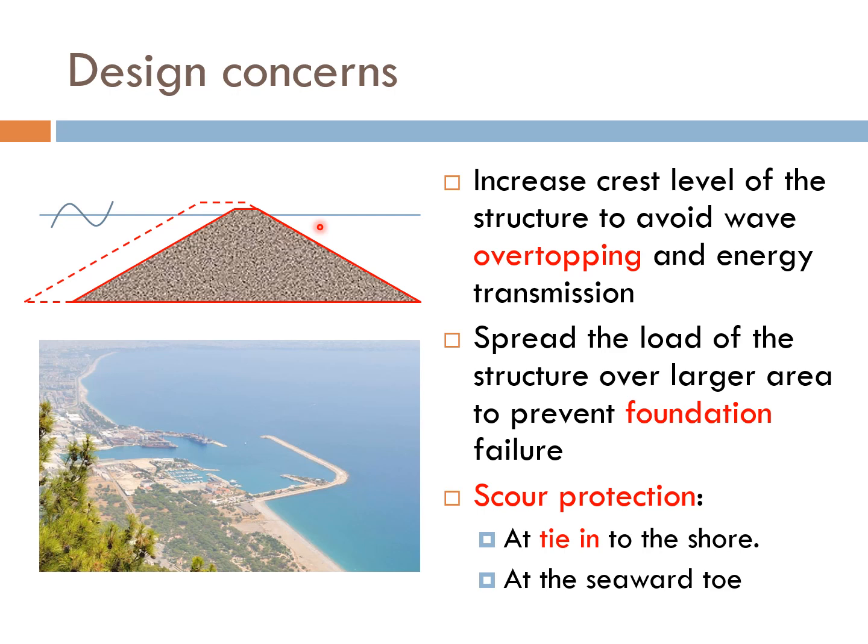Also, spreading the load of the structure over a larger area can help to prevent the risk of foundation failure. However, both these approaches mean that the breakwater is likely to be much larger, and that usually would translate to high construction and initial cost for this particular option.